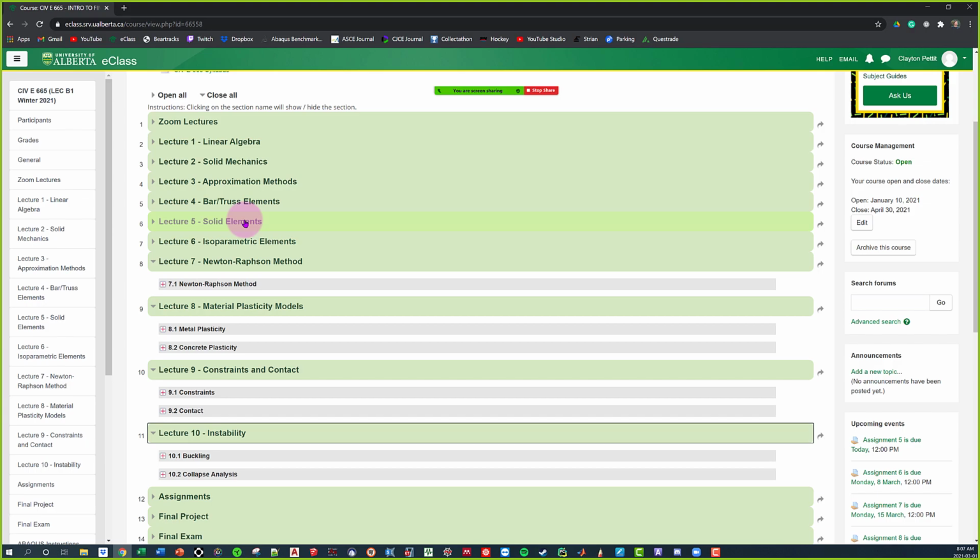What happens in beam elements, and what also happens in shell elements, is they have that rotational degree of freedom. Now remember, when we were dealing with these solid elements in ABAQUS, a lot of you guys said I need to restrict the rotation. But I said, well, it's actually kind of a trick, where these solid elements don't have that degree of freedom associated with rotation, so we don't actually need to restrict it.